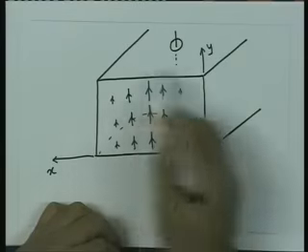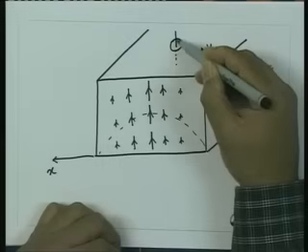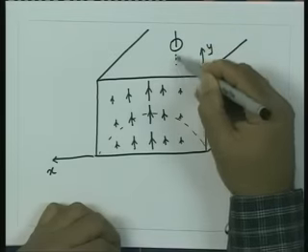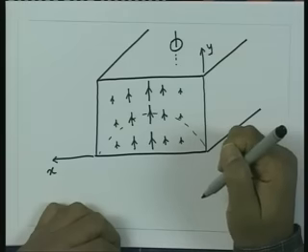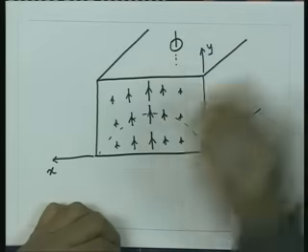Only the frequency for which the cutoff frequency is less than the signal frequency will travel, and if you make sure that the frequency is larger than the cutoff frequency of the TE10 mode but smaller than any other cutoff frequency, you get a guaranteed TE10 mode inside the waveguiding structure. So essentially a TE10 mode inside a waveguide can be excited by putting a probe which can excite electric field inside the waveguide at the middle of the broader wall.